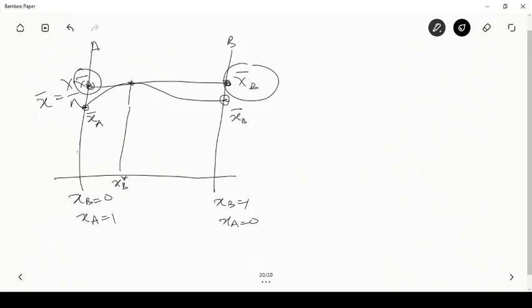But when I have an n component system, this measurement becomes extremely painstaking, and we won't have a two-dimensional graph here, but a multi-dimensional hypersurface, and it will be calculating gradients at each location, and you will need to take slices of that and treat it like a binary mixture, species I and the rest of the mixture. The rest of the mixture is treated like one substance and species I is treated as another substance, and you do the variation of this kind, and you do that for every other composition of the rest of the mixture. So that is how you measure partial molar properties.